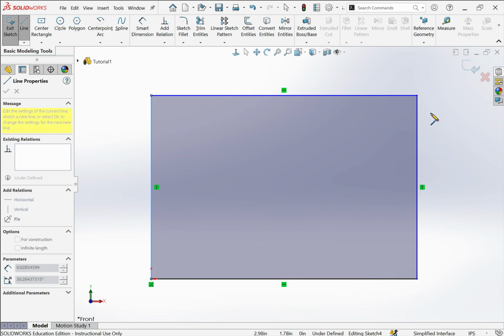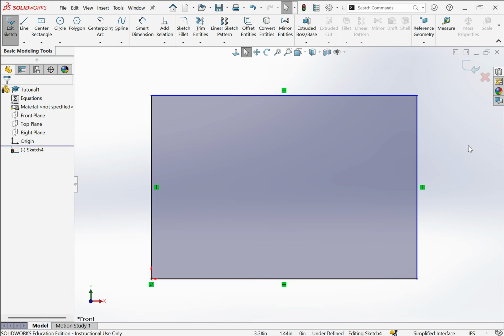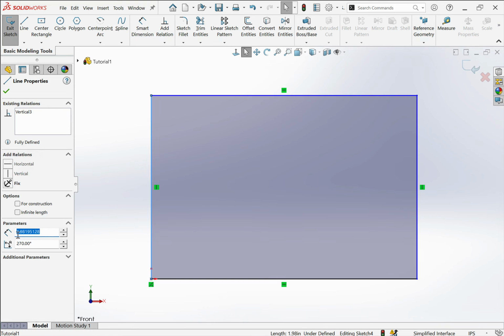Now also notice that I have this line sketch thing, this little icon. If you simply hit escape, it gets you out of that. Escape will get you out of a lot of operations. If you want to create more lines, that's fine, but we already have some inside object that we can project into 3 dimensions, okay?